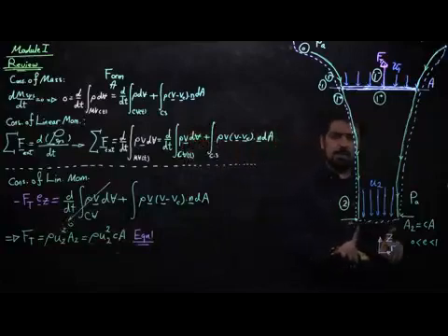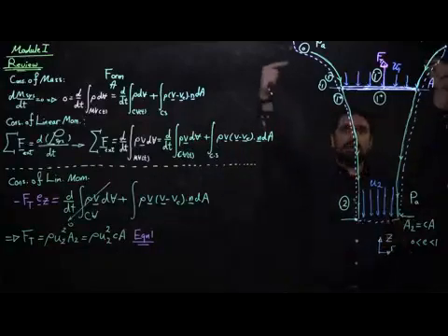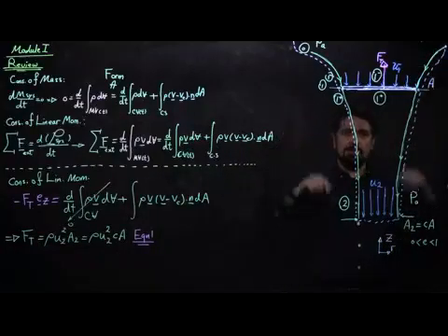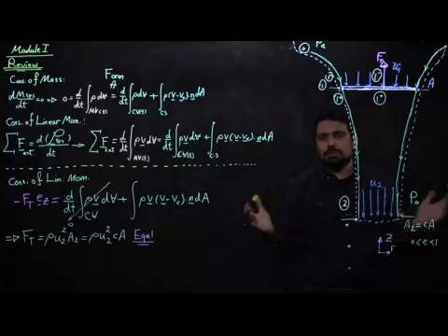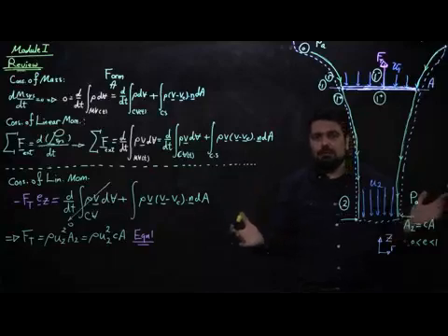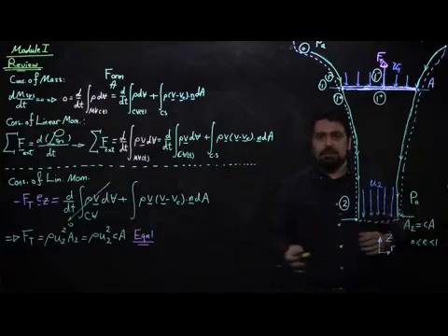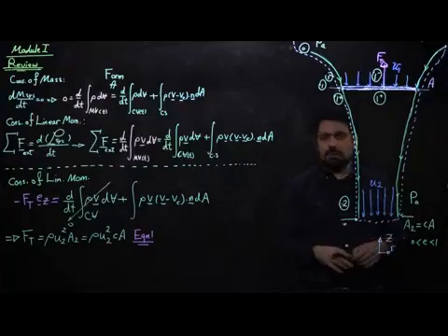The only pressures that are giving me components in the z are atmospheric at the bottom and the top, and the atmospheric pressure can be taken out of the system altogether, because when you take a scalar away from a pressure field and integrate the entire force of that pressure field around the closed object based on Gauss theorem, that would be zero contribution, so we can take atmospheric out.